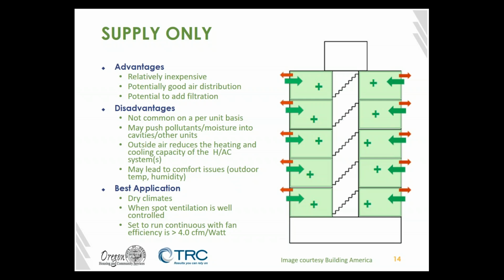And similarly, the pollutants and the moisture and the toxins you're pushing out might just be collecting in places. They're collecting in the cavities and the cracks and the seams, and they're not really going away. They're just going somewhere slightly different, and maybe accumulating there in negative ways. And then similarly, you're hurting your energy a little bit by ditching some of the quality, conditioned air that you have in the house without taking some of the energy back out of it.